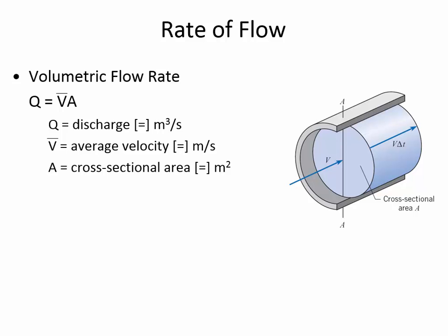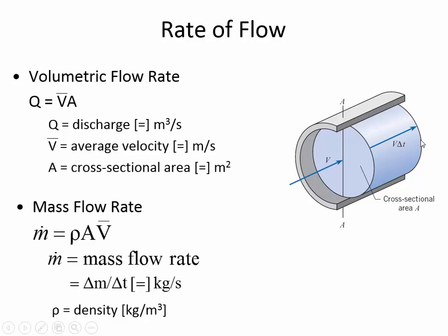The diagram shown here is saying that if the velocity is known and the period of time that the water is flowing is known, then you end up with a volume of water, a certain quantity. If the velocity is in meters per second, for example, and you multiply that by a certain amount of time, then with the cross-sectional area you can find the flow rate, and an increment of time would give you a volume. So volumetric flow rate is one way to express it, and the other is mass flow rate.